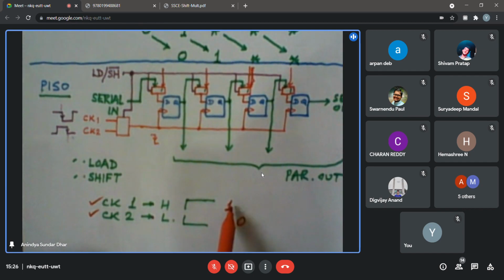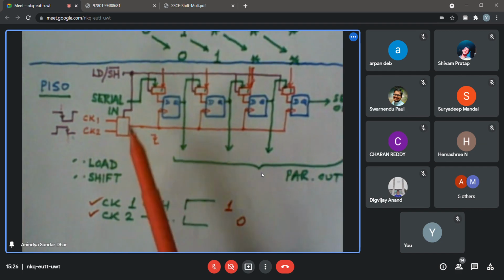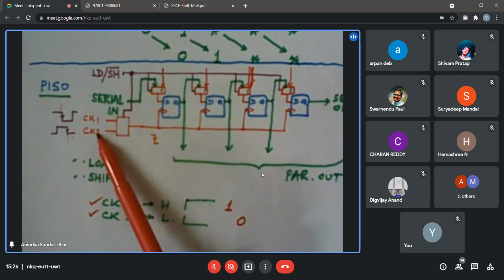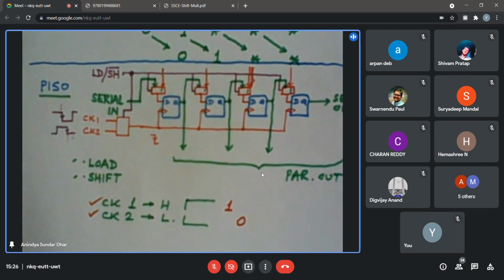So do you appreciate that problem? There is no falling edge in either clock 1 or clock 2, just because of the changing of the load shift control at an inappropriate moment, that has given rise to a spurious clock edge. So is that problem clear?